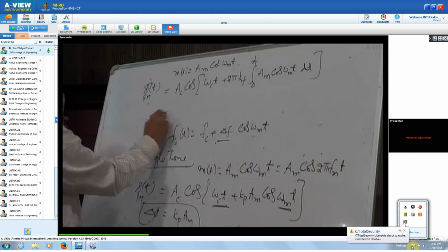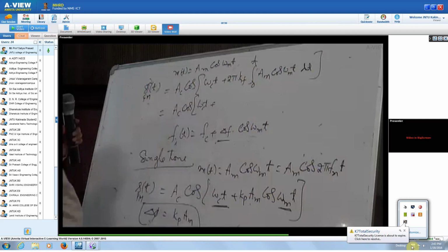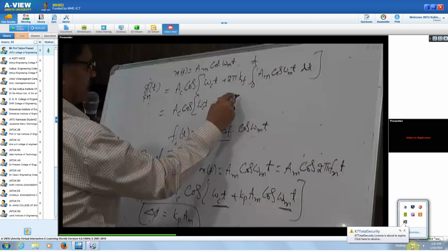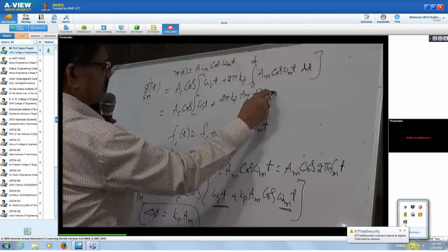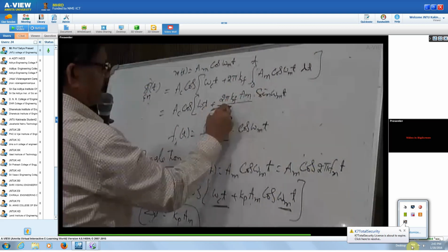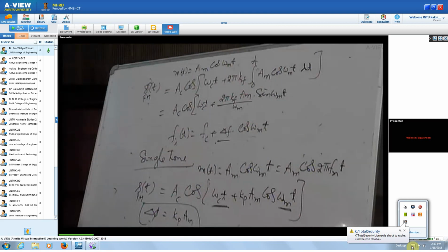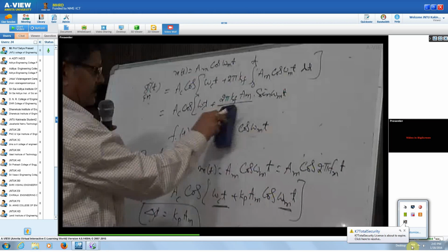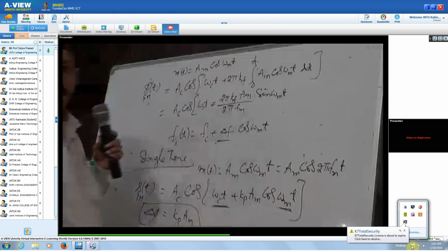This will be equal to Ac cos omega c t plus 2 pi kf Am sin omega m t by omega m. Or this I will write as 2 pi Fm.